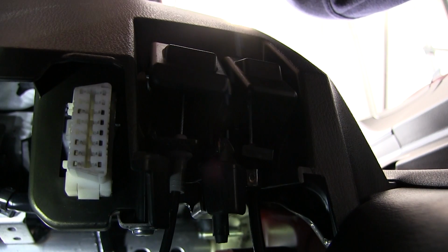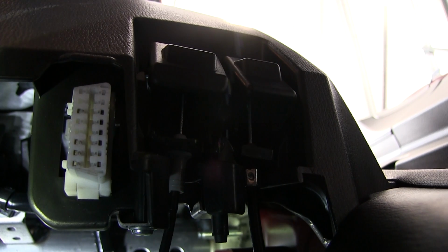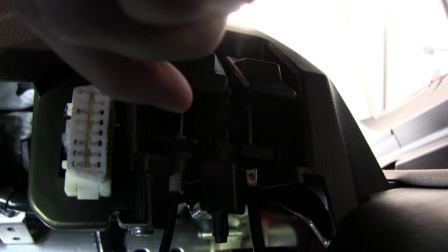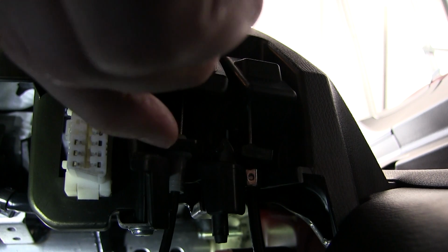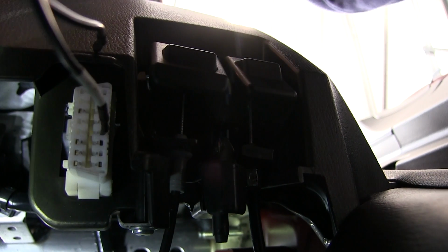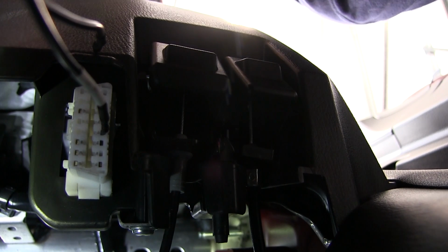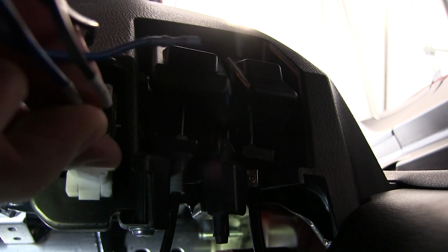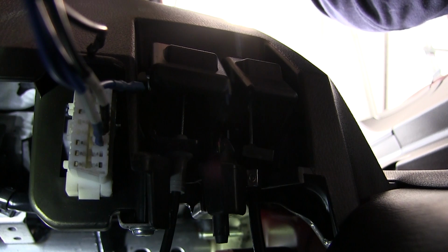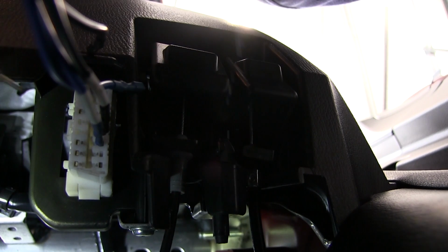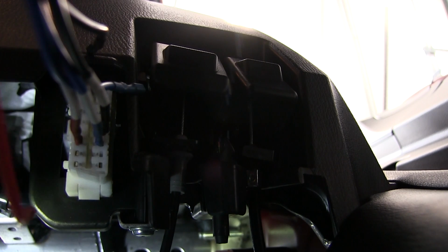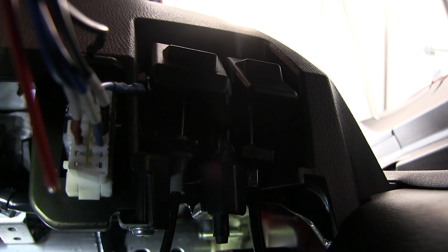Okay, so we're down here at the diagnostic link connector, which is the white connector on the edge of your screen. I'm going to connect our three terminals. So we want our earth first, which we'll put on terminal 5. So there's number 5 on the top. Then I'll put CAN high, terminal number 6 next to it. And then directly opposite that, we've got our CAN low on terminal 14. An easy way to get to that is we've got 16, 15, 14 from the top at the back.